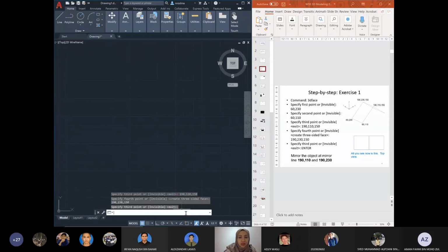Okay, so where is the drawing? How do we look for your drawing? If you still remember, how do you do it? It's somewhere there. Z enter, A enter. Yes, you can zoom all or zoom extents. So Z, or you can type in zoom and enter, and then you can choose all or extents or window, anything. Okay, let's do extents.